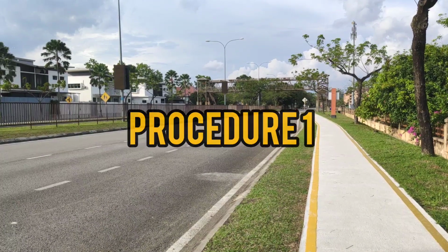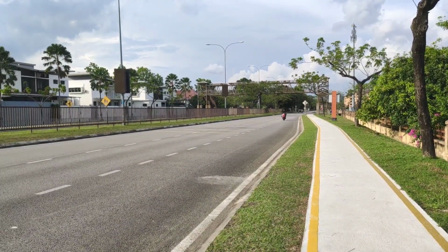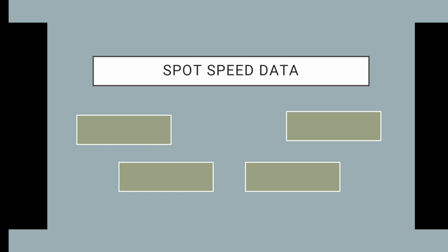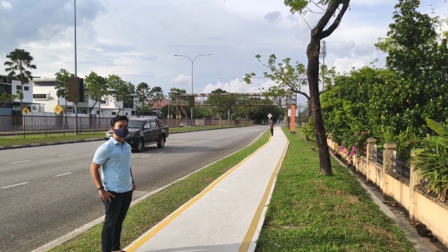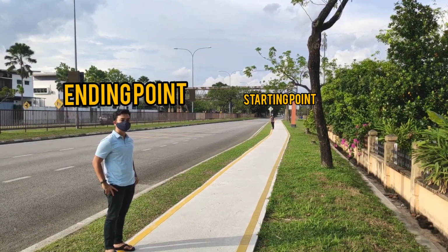Stopwatch method. A suitable location was decided and appropriate study length obtained, which was minimum 100 meter distance, long enough for reliable observer reaction time. On the stopwatch spot speed data form, the observer should record the date, location, weather condition, start time, end time, and plate numbers of random target vehicles. Two reference points were selected as starting point and ending point along the 100 meter distance.